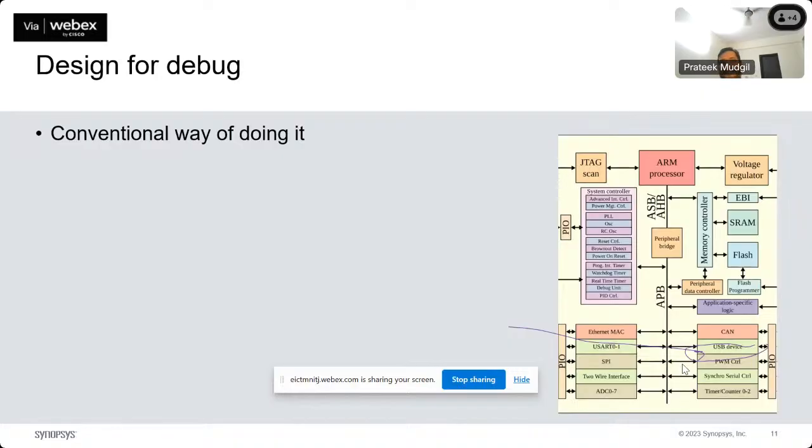And when it fails, if there is a silicon debug, or a functional bug inside block B, the vendor will not own any responsibility, saying, you have touched it. You just put a comment in my area. Let us say there are RTL files in any block, and you just went inside and did not make any RTL change, not any logical change. You just put a comment there, a slash comment, and then you synthesize it, and the chip got taped out, and the silicon stopped working. Somehow vendor B will say, see, you have edited it, I don't own the responsibility. So that's how the industry works, right? We are not allowed to edit the blocks.